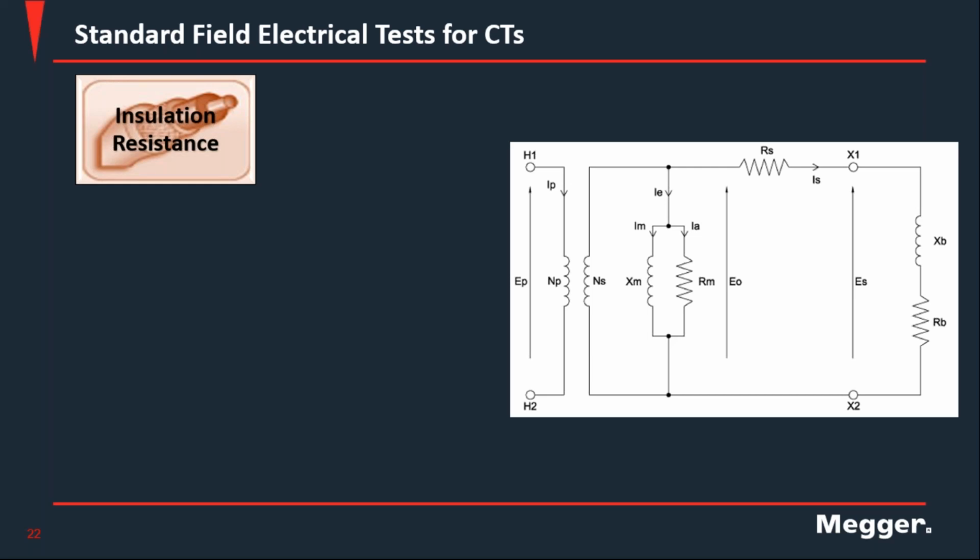But depending on the type of CT or VT, the voltage level, the current level, you may have oil insulation, or paper, cellulose immersed insulation. You can also have resins. So you have different insulations where sometimes just a simple insulation resistance at 500 V or 1 kV may not be enough. You need to consider other insulation assessment tools.